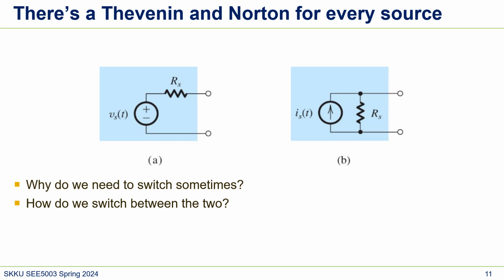So far, we talked about Thevenin and Norton, the basics. One thing that's really important is that every linear electrical circuit can be replaced by either Thevenin or Norton sources. The important thing here is that a Thevenin source must have a single voltage source and a single resistor, and a Norton source must have one single current source and a parallel input resistor. And then we also did some basic calculation.